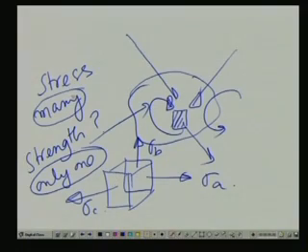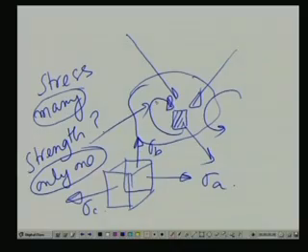So, unlike the simplest situation, here we have to find out the stress at a typical point, or at the different points we primarily talk about as critical points, and only then can we equate it with the strength of the material, which is on one side. You can consider the yield strength of the material or the ultimate strength of the material. So the strength of the material is basically one.